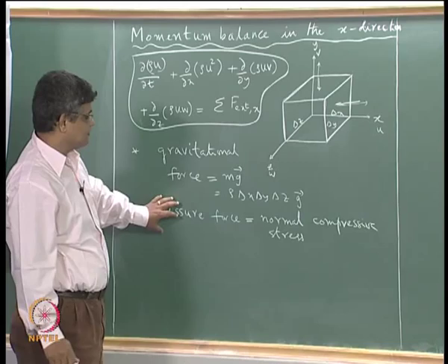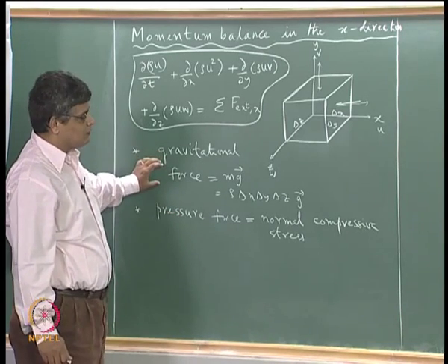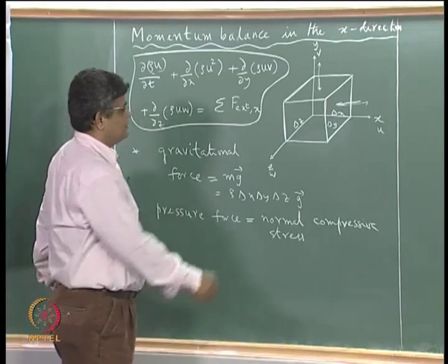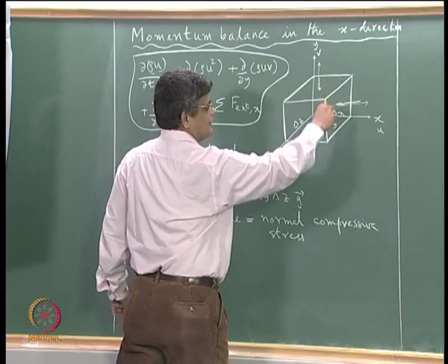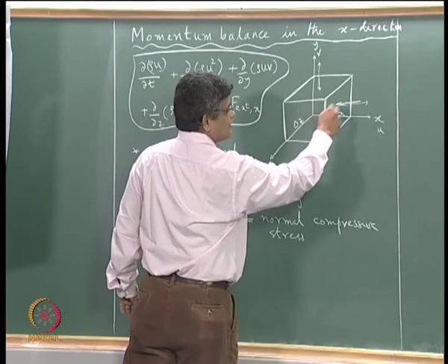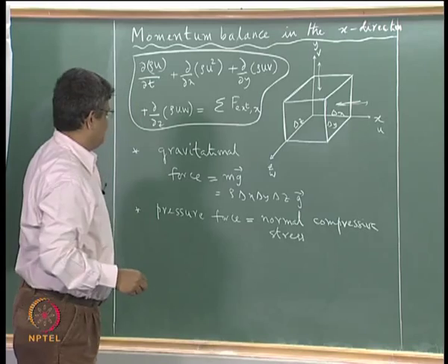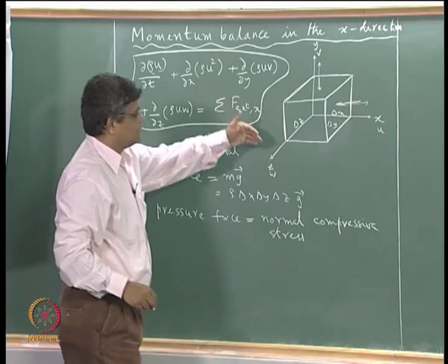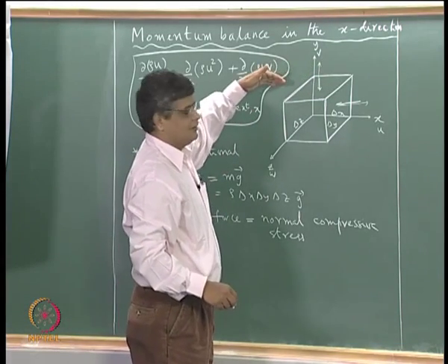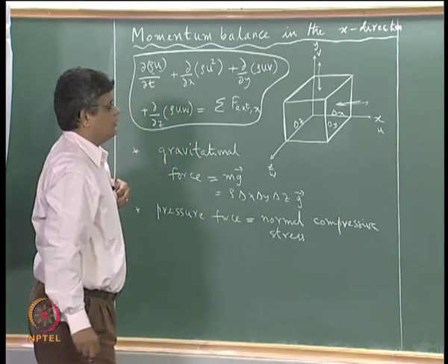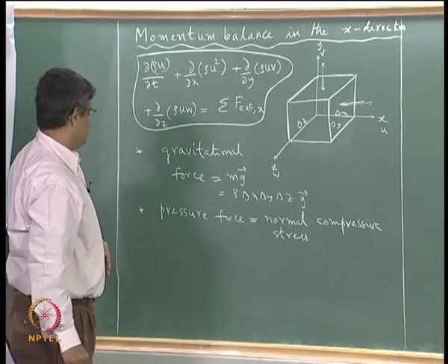So we would like to distinguish between a gravitational force, which is a body force acting essentially on every fluid particle contained within this, and the pressure force, which is acting only on the surfaces of the body by the fluid external to this.